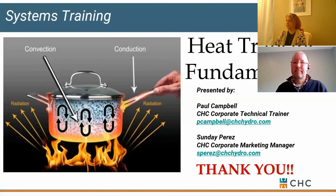Okay, one more question just came in. Can you get extra heat transfer by increasing flow rate on one side of the heat exchanger? You can, but it's a tricky one. We see a lot of summer and winter conditions, and you always have to pick the worst case and look at your total surface area. Then we can do a performance for your worst case load. But we never know whether it's summer or winter, which is driving your total plate count or surface area. Can you get more performance? You can. You have to be careful.